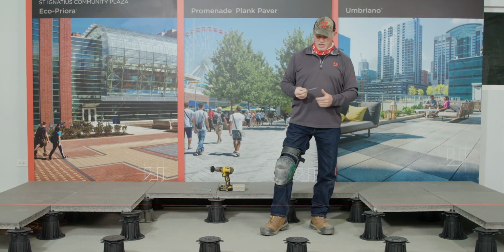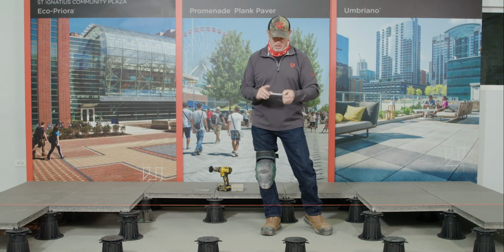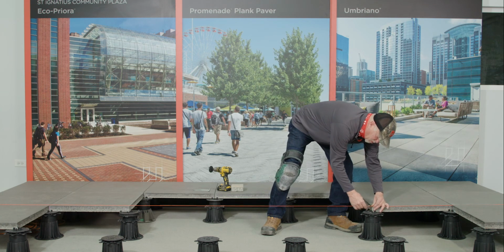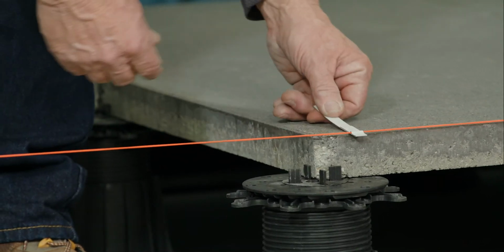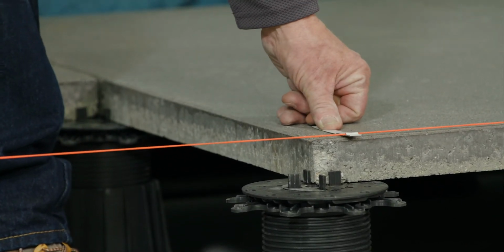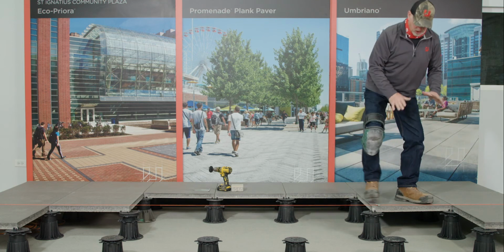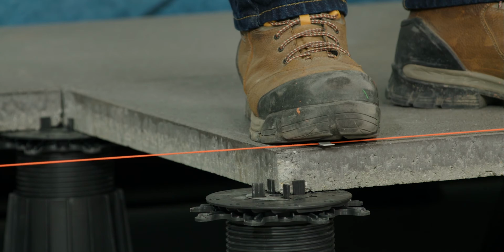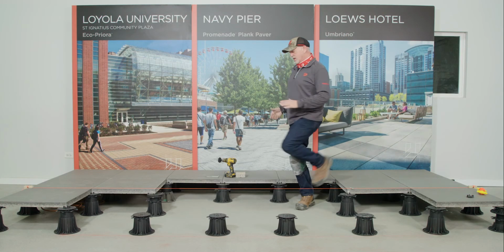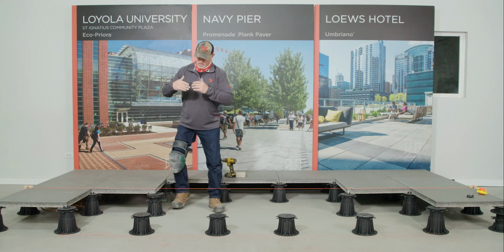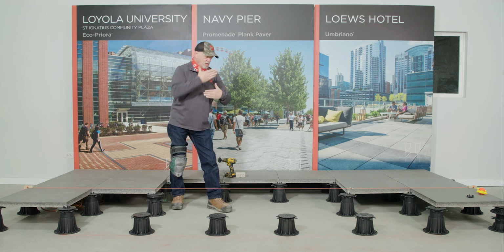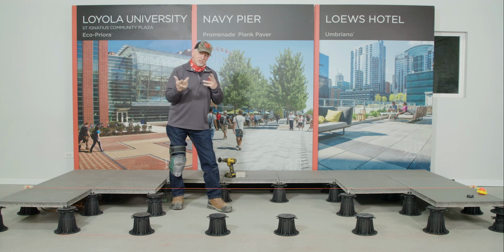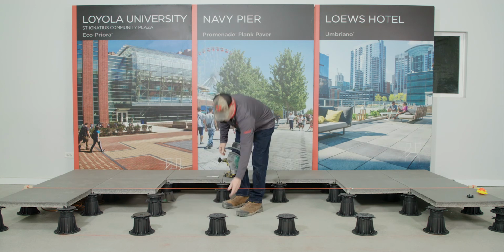So if you're doing a center point, oftentimes you'll see a trig used in masonry as well. That clips onto the line at that center point, right inside of that line, and accurately holds that line in place. So now, from this position, we can be working to the right as well as to the left and have two crews on that job. The other thing that I like about the dry line is that it's setting my elevation point as well as its pattern guide. That's one nice thing that assists the installation.